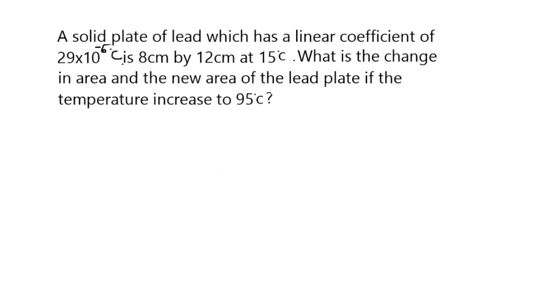Now let's move on and just solve this problem. Example problem. A solid plate of lead which has a linear coefficient of 29 times 10 raised to the negative 6, dapat over degree Celsius yan, is 8 cm by 12 cm at 15 degrees Celsius. What is the change in area and the new area of the lead plate if the temperature increases to 95 degrees Celsius? So, sabi dito, meron tayong plate of lead.